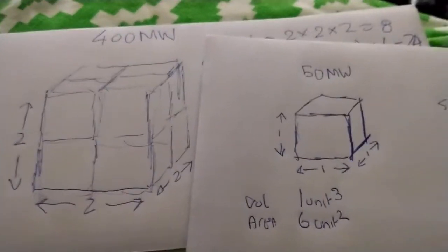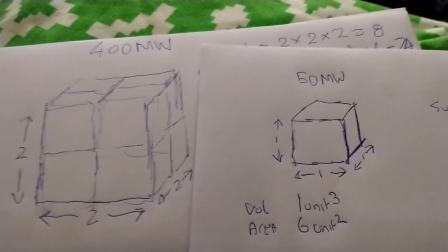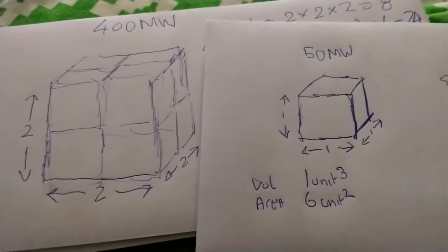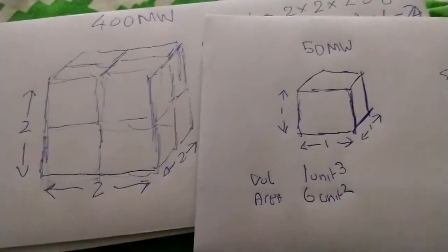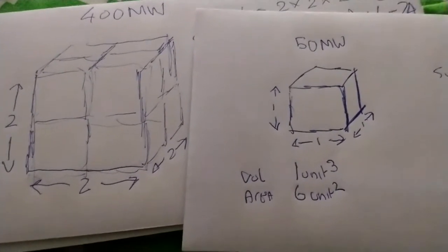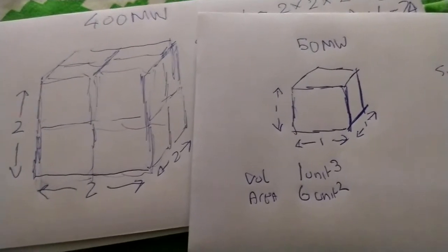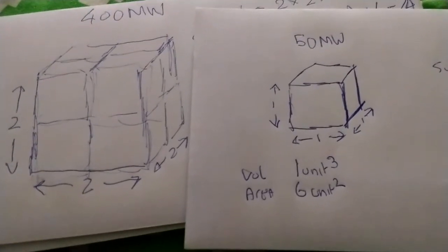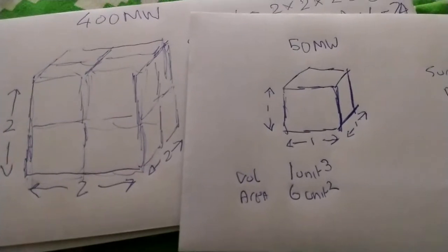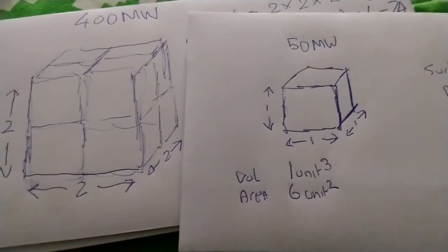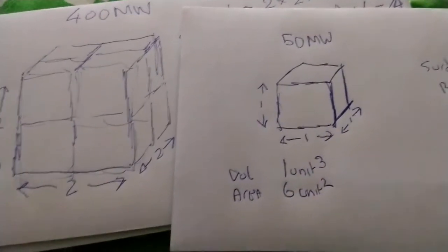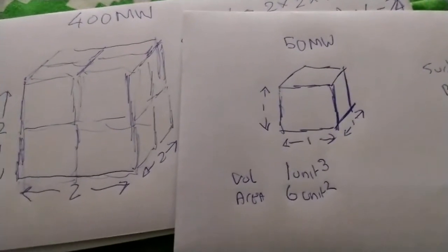So if the reactor was taken offline, you could pump out the cooling water around it using electricity off the national grid to keep it cool. If that broke down, there was then a set of on-site generators, quite capable of replicating what the grid did, that could run for as long as you could put fuel in them. So even if they ran out of fuel after a few days, you could just get a tank of fuel and top it in there and keep things cool.